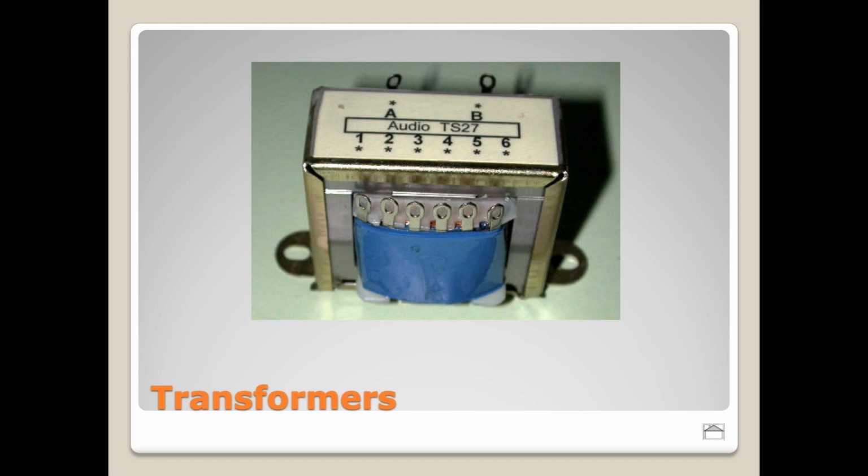But just blindly grabbing a transformer off the shelf and hoping that it's going to do the job for you usually doesn't work very well. So transformers, again, very, very important. As we continue on through the semester, we are going to talk more about how a power supply comes together. But remember, this is that first foundational piece. When electricity comes in from the wall, it's going to hit one of these first, right? Because we have to generate those multiple voltages out that we need for our piece of equipment to function.